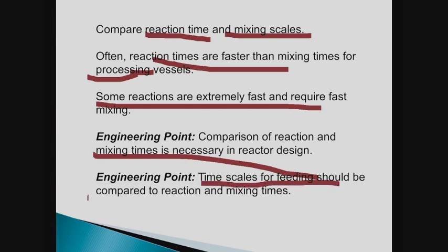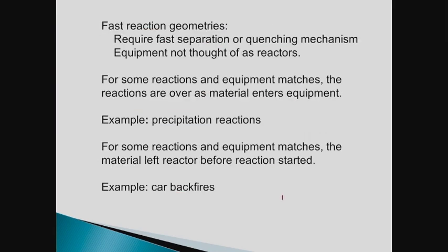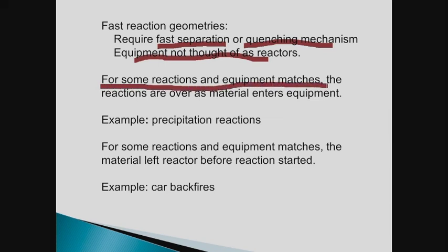Timescales for feeding should be compared to the reaction and mixing time. It takes a long time sometimes to feed something. Fast reaction geometries may require a fast separation or quenching mechanism. So the equipment is not thought of as a reactor. Some reactions and equipment match.